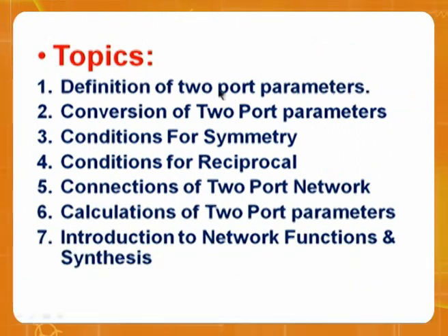First thing, the topics. Definition of two-port parameters. What are the definitions? Then I will take you to conversion of two-port parameters, how to convert one parameter into another parameter. Then conditions for symmetry. Symmetry means the input and outputs, if the impedances are equal, we call symmetry. Reciprocal also we see the conditions. Reciprocal means the transfer impedances are equal.